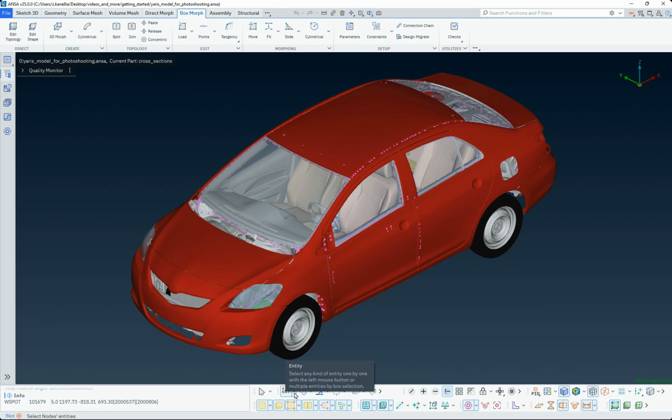The next group is the Select From group. The user can choose from where to select nodes or entities. There are different options such as PID, Part, PID region, connectivity, color, and draw mode, which follows the current draw mode that is selected. In the PID region, there are some options regarding the bounds that will cause the method to stop expansion. Angle is a separate group.